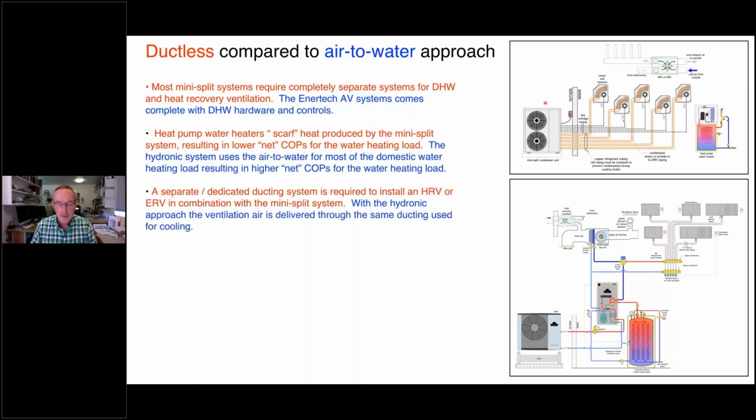Whereas with a hydronic system, all that energy is going into that domestic water tank. Now, I'm going to go back and correct myself on that. Most of the energy going into that domestic water tank is coming from the heat pump. There is the possibility that there are electric elements that would heat that.